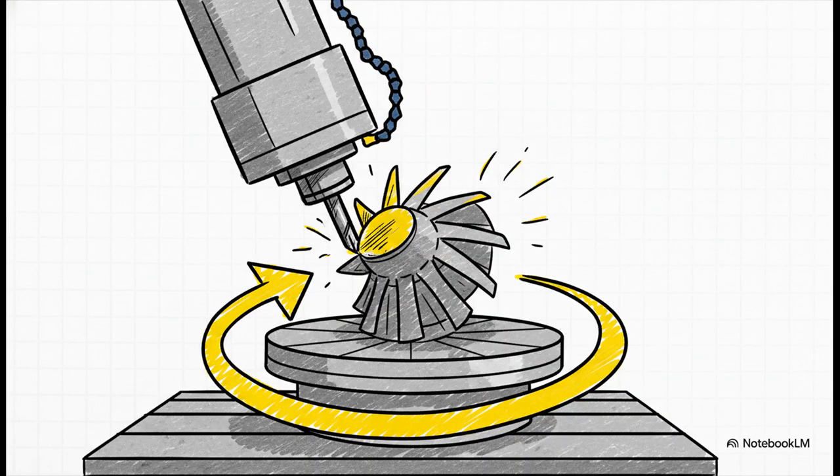And for the grand finale, we'll add a C-axis, which rotates the table that the part is sitting on. When you combine the linear movements of X, Y, and Z with the tool tilting from the A-axis and the part rotation from the C-axis, boom, you've got full 5-axis control. This is exactly how you machine those incredibly complex parts like aerospace turbine blades all in one go.